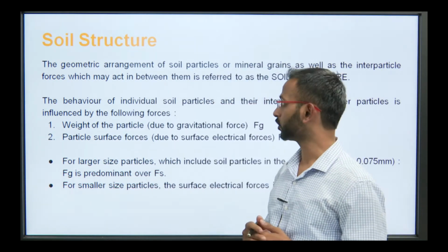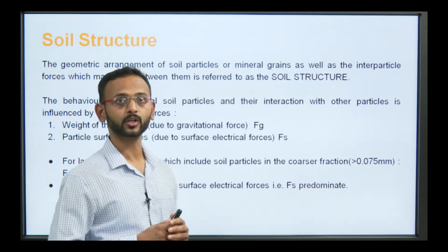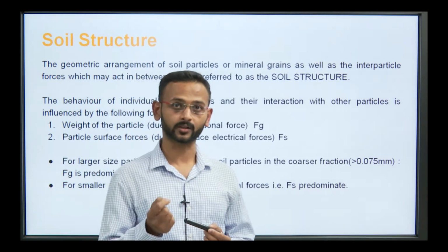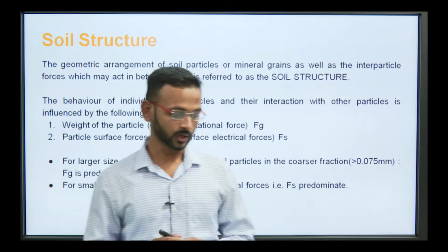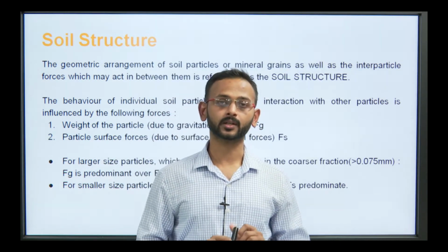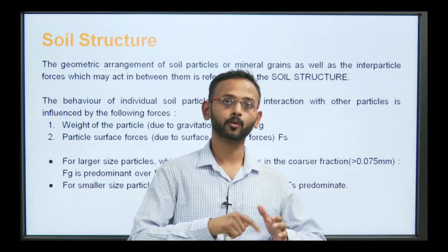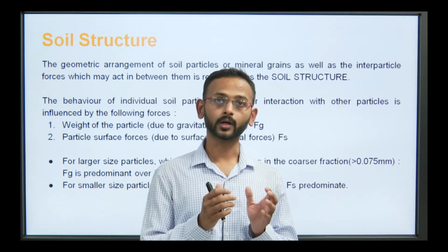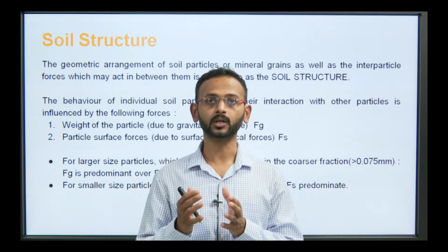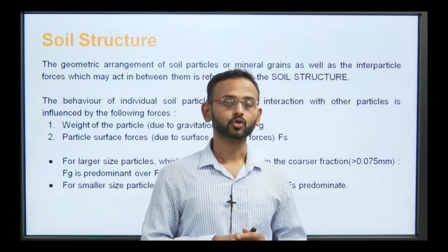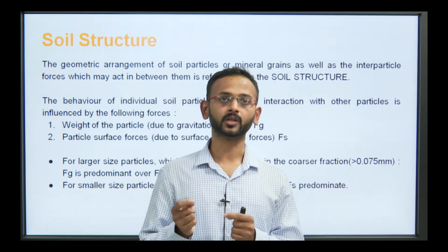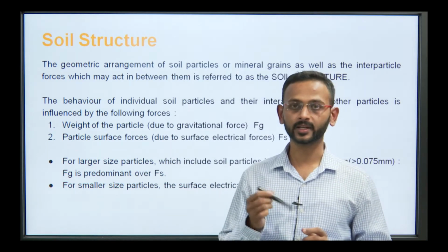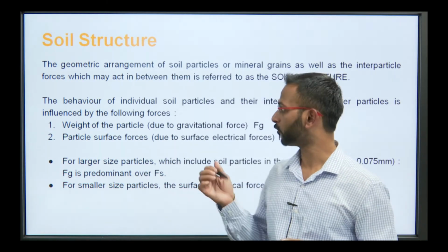In this soil structure topic, the geometric arrangement of the soil particles or mineral grains, as well as the interparticle forces which may act between them, is referred to as the soil structure. Remember one thing: first of all we will be discussing what type of structure, but there are also some forces which will be acting in between the particles, or the particles would be exerting on the other particles also. Studying of this behavior will be constituted into two forces: the behavior of the individual soil particles and their interaction with other particles is influenced by the following forces.